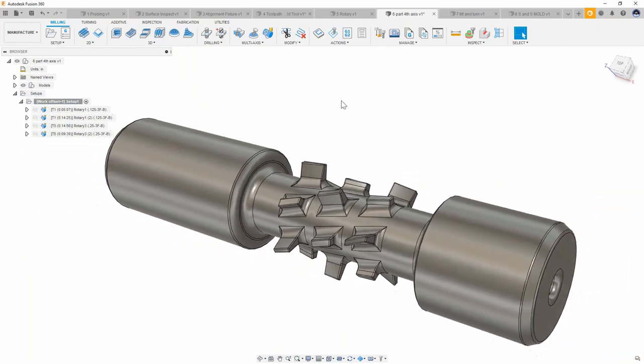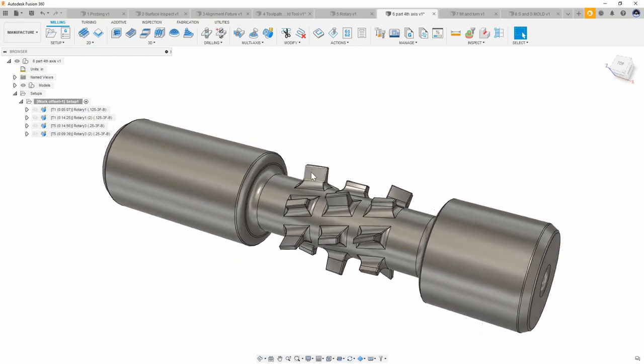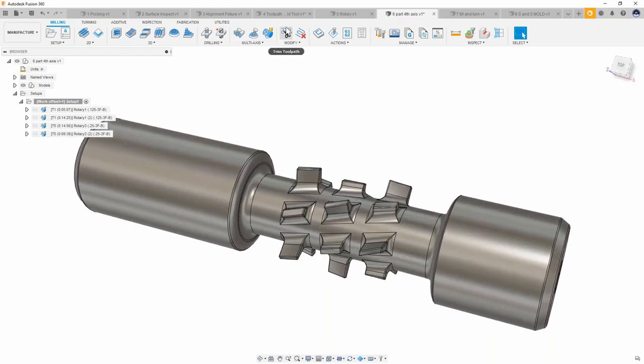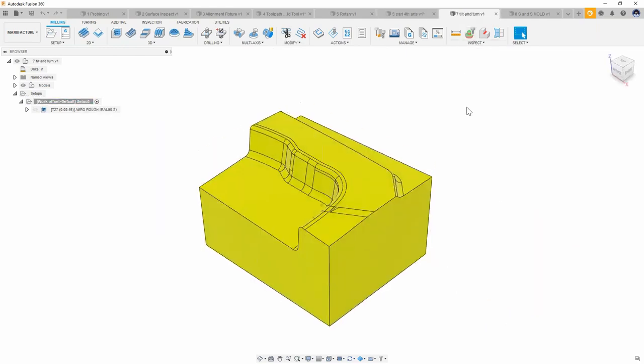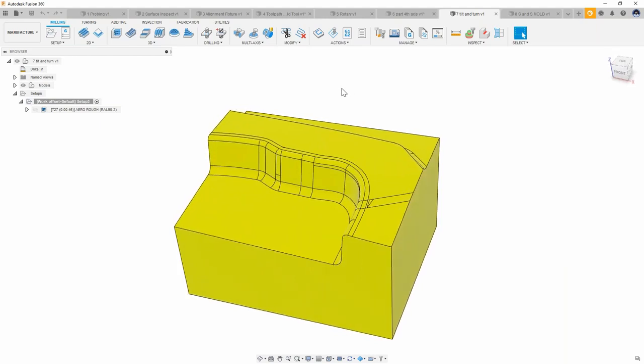So that's about it for rotary. And we can also use the toolpath trimming on this rotary toolpath. So maybe we want to omit certain areas or certain fins, or maybe one of these is missing. We can certainly do that with those edit functions that I showed earlier. Let's move to tilt and turn, which is some of my favorite stuff. So this is getting into some of the 5-axis, right?